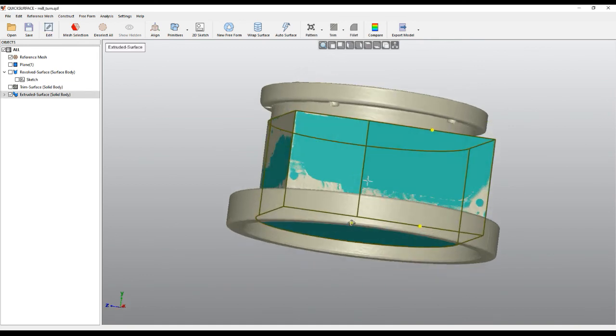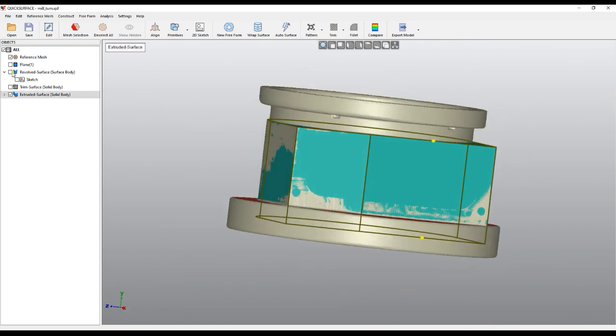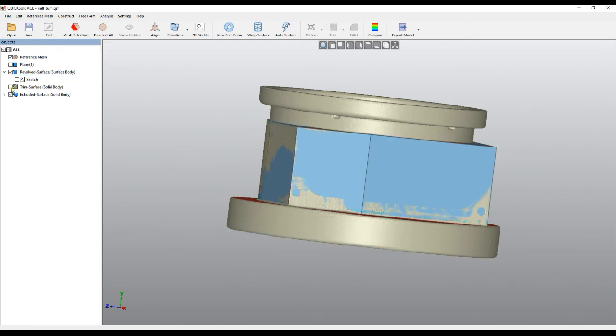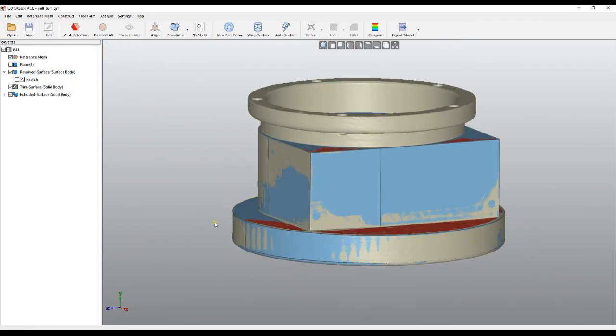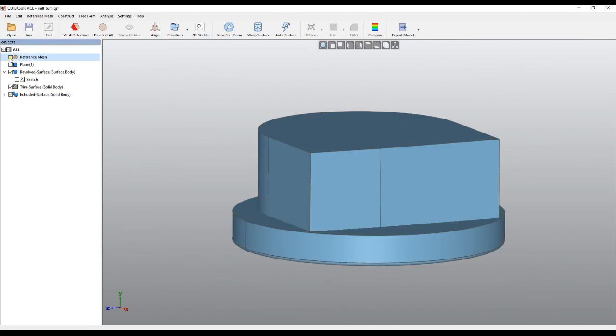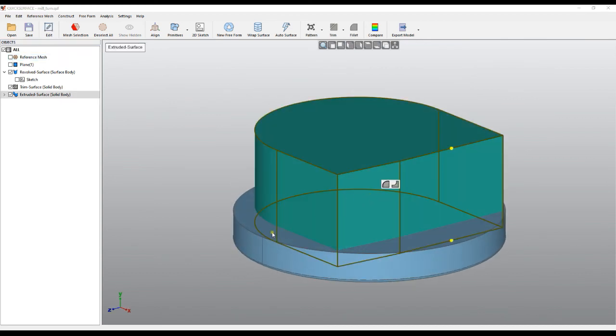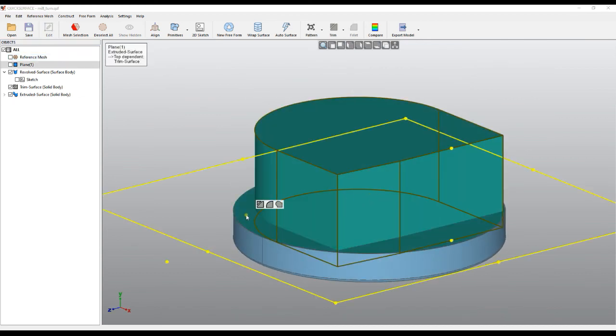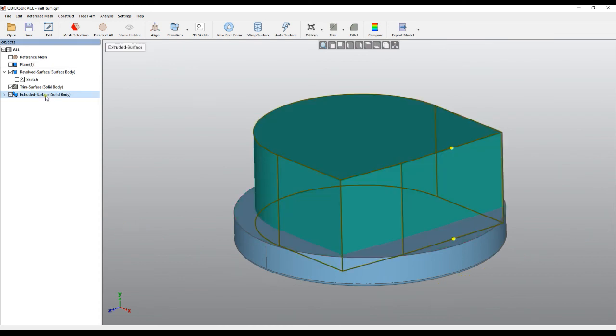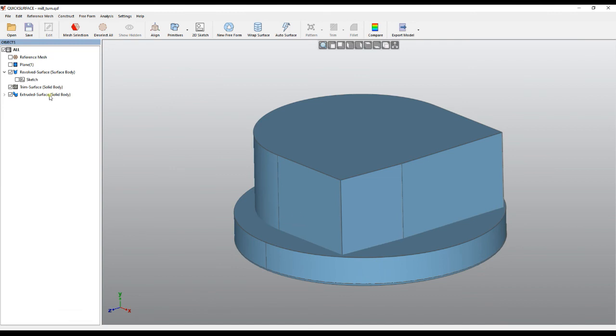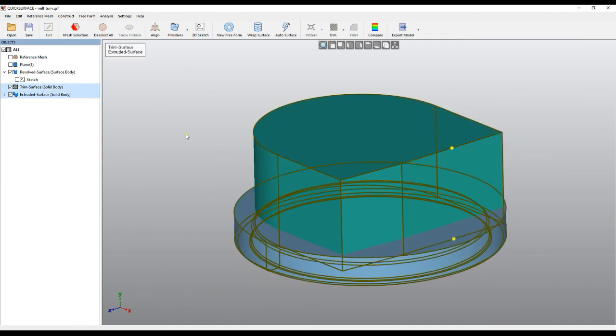Now I have this a little bit more extended like this one, and I can do now the standard Boolean operation, which I'll hide the mesh, and actually take these two with the control. I'll select both of them, and I can select combine selected solid, which failed in this case because it selected the base reference. So if you get this message, you actually select the two which are of interest. Use the entity tree, and then